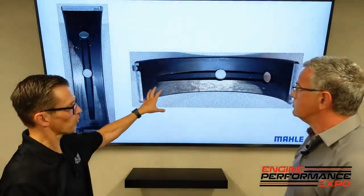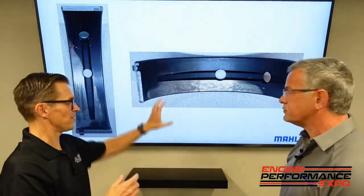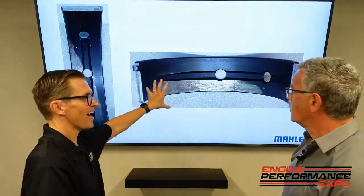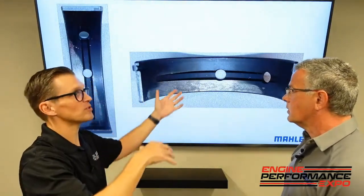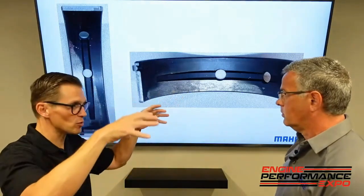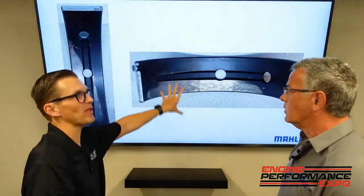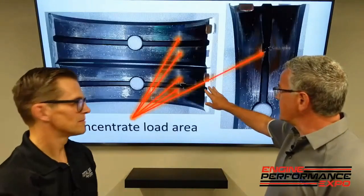And this is really important to understand for choosing bearing clearance. Actually, very true. This would be a limit of how tight you can run your bearing clearance is how stiff or much motion there is in your crankshaft. The more your crankshaft moves, the more clearance you're going to have to give it to allow for that deflection. Until you run out of oil flow. Right. Yeah.